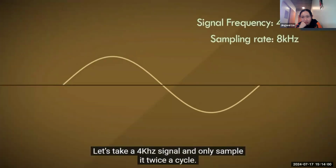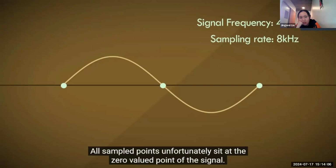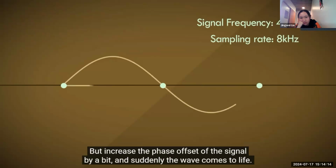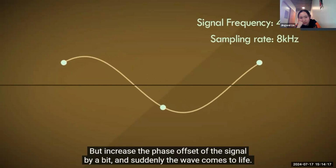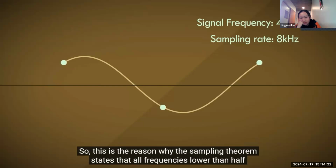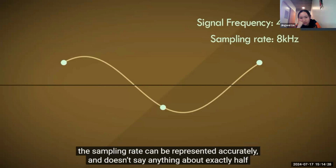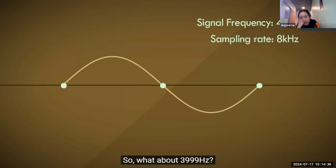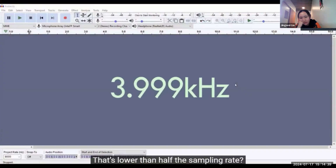Let's take a 4 kHz signal and only sample it twice a cycle. This is the current situation. All sampled points, unfortunately, sit at the zero valued point of the signal. So naturally, this is interpreted as no signal at all. But increase the phase offset of the signal by just a bit, and suddenly the wave comes to life. So this is the reason why the sampling theorem states that all frequencies lower than half the sampling rate can be represented accurately, and doesn't say anything about exactly half the sample rate, because it wouldn't be an accurate representation for all scenarios. So what about 3,999 Hz?